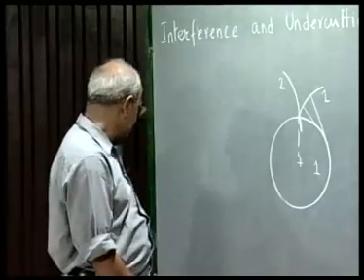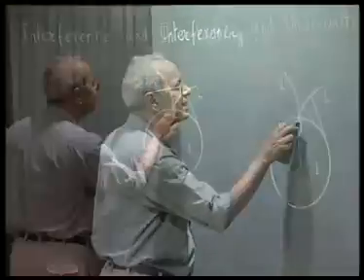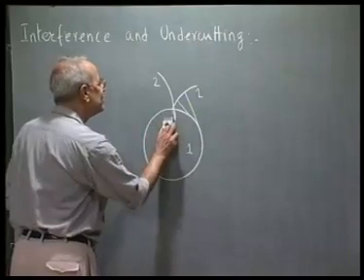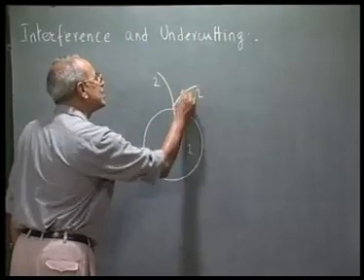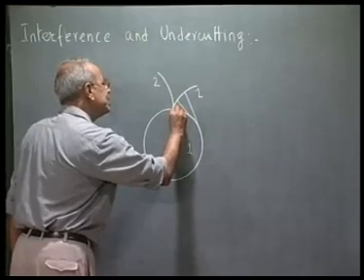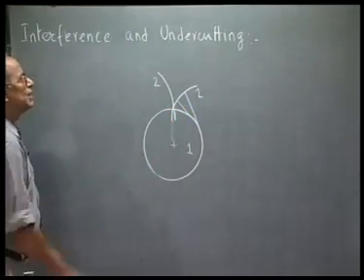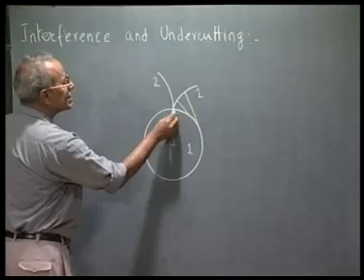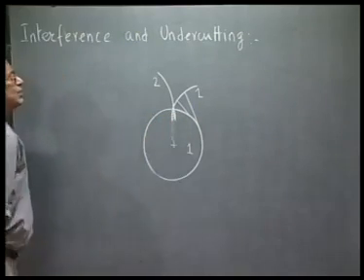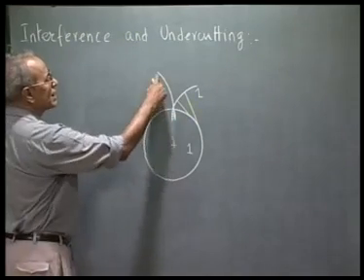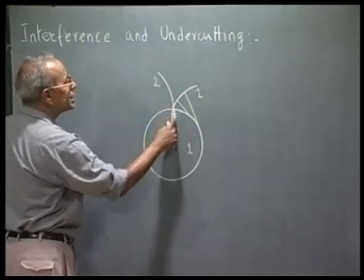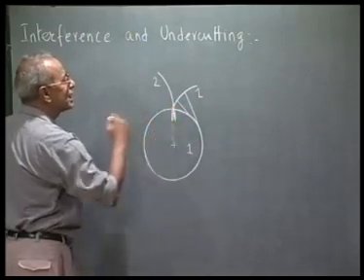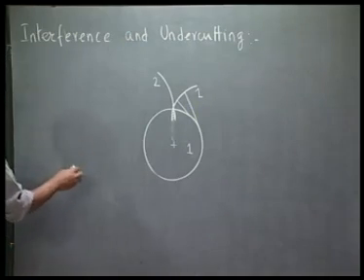So what one can do, one can extend this involute of gear 1 maybe radially. Even then there is interference. As we see, this tooth will interfere with this tooth because this tooth wants to occupy this position, whereas this tooth is lying there. This is called interference.